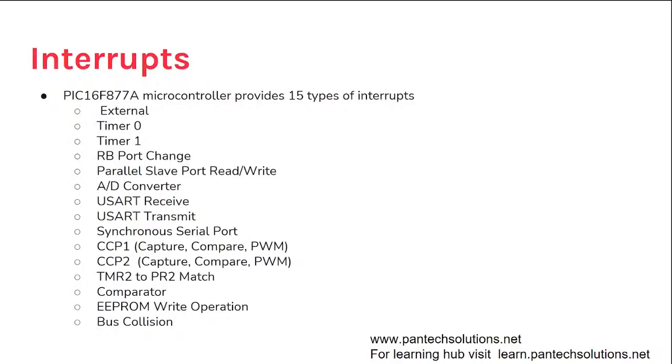It could support external interrupts, interrupts from timer 0 and timer 1, RB port change, parallel slave port read or write operations, A/D analog to digital converter operations, USART receive and transmit operations, synchronous serial port (SSP) operations, capture, compare, PWM (CCP1 and CCP2), TMR2, comparator, EEPROM write operation, and bus collision. So all this can generate interrupts.